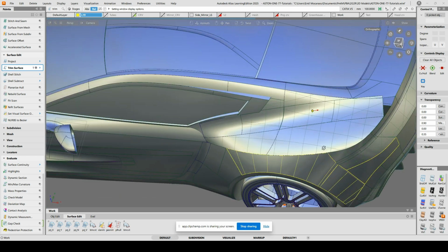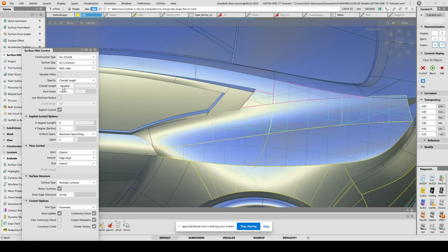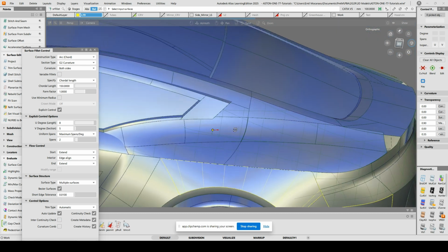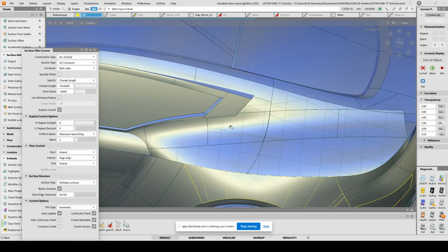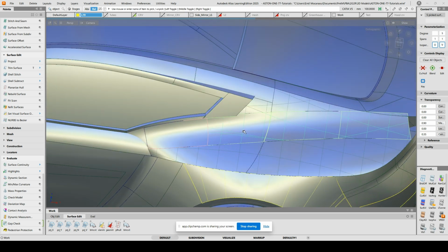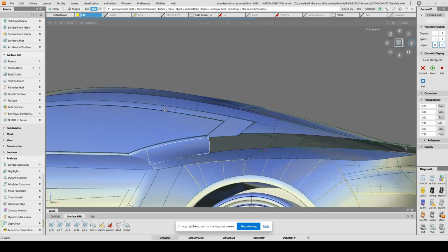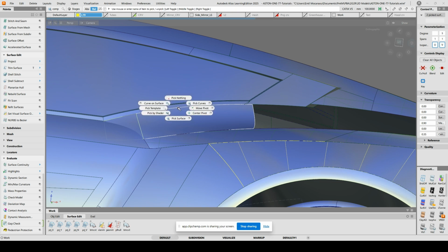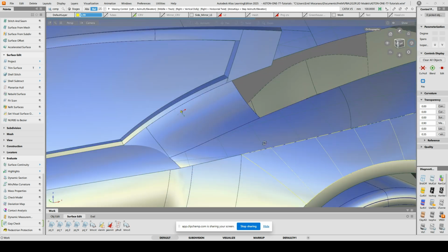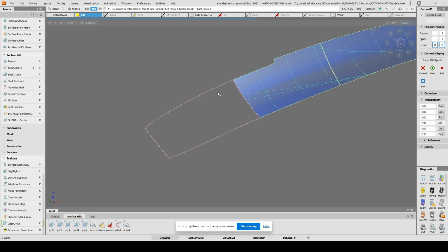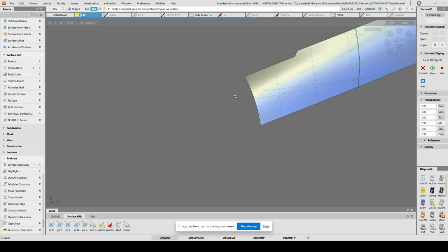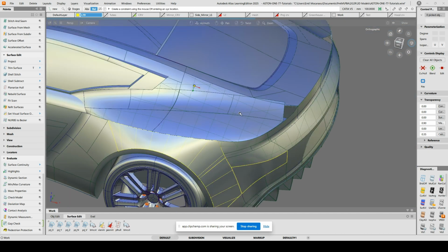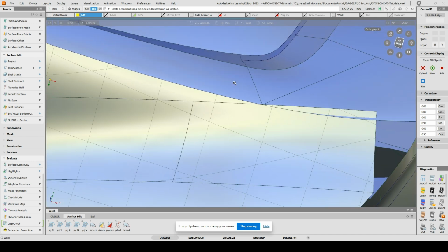And the way I've done that, I've made a 150 radius between that surface and that one. That's easy peasy. That's running up to this point here. And then come up with two more surfaces that connect from that radius up to that rail there. So that surface is derived off of the radius, that little bit there. And that final bit is just closing that up so I see how things are working, and it's giving me an idea of what we will be doing at a later stage.